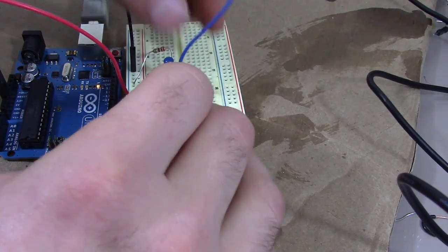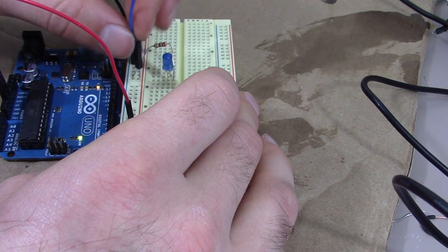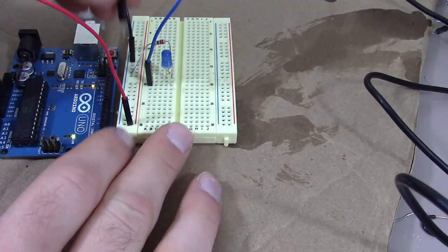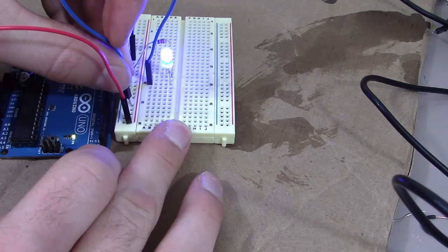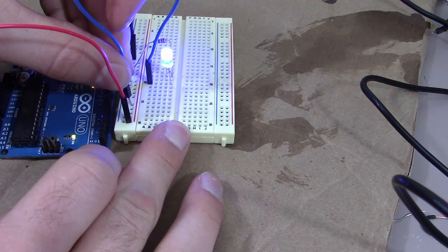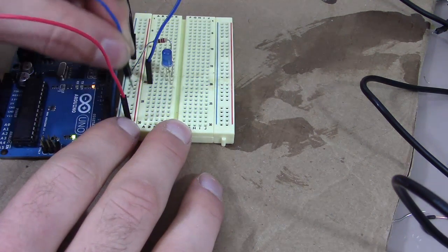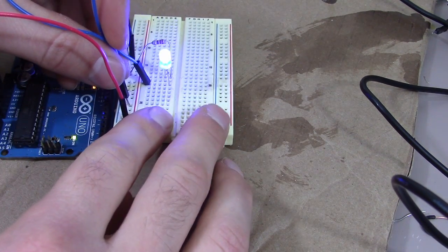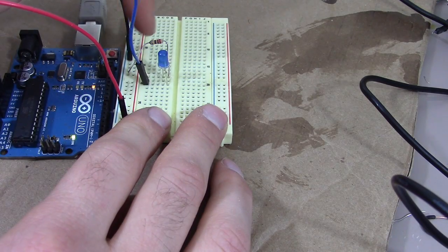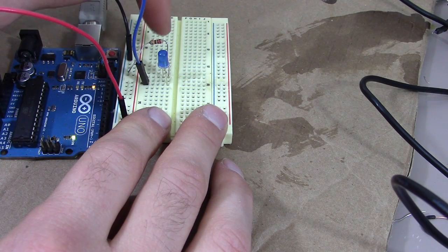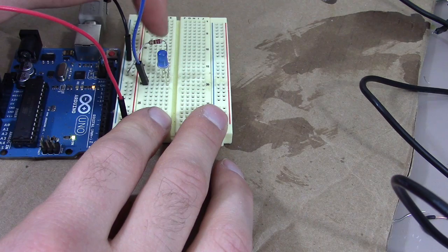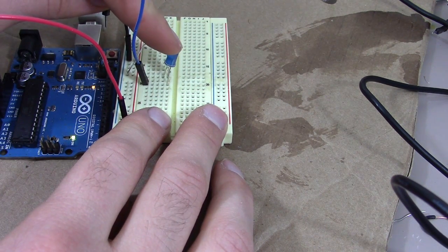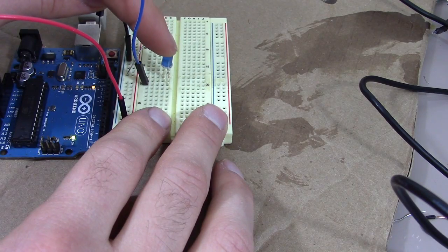And just to test and make sure that the LED is actually turning on, let's go ahead and test it, and I can connect this to power, my 5 volts right here. Boom, LED is working, fantastic. So that is 8 milliamps going through this LED to turn it on right now. So you could essentially change out this resistor plenty of times to make it higher or lower, and that would change the brightness of this LED. But make sure you do your math and don't ever go over 20 milliamps.